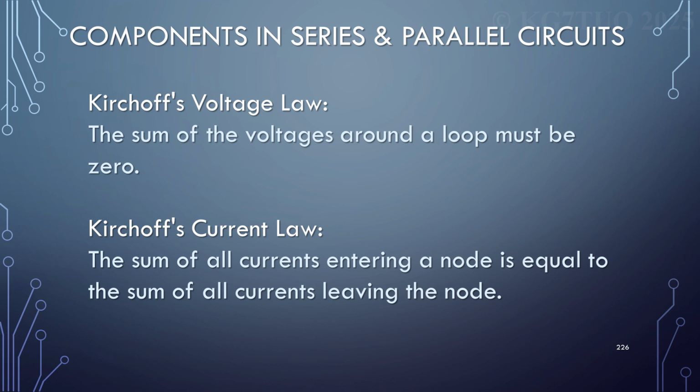The reality is electrons flow from the minus to the plus. So maybe that's part of the reason why you will find a fuse in both leads on a radio. Yep. Well, there's another reason for that. It's because if your negative lead shorts, you've got some protection.